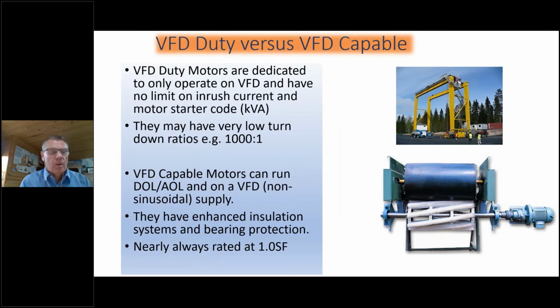This is almost a summary now. The biggest question I get asked when I'm doing trade show events, or people come around and say, hey, what's the difference between VFD Duty and VFD Capable? Well, they actually are different animals. They are actually different types of motors. And NEMA MG1 addresses that. If you pull the standard, there's a Part 30 and a Part 31. Part 30 deals with